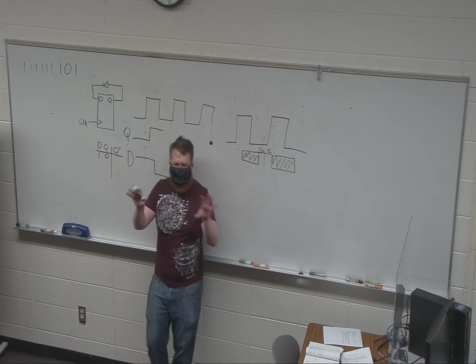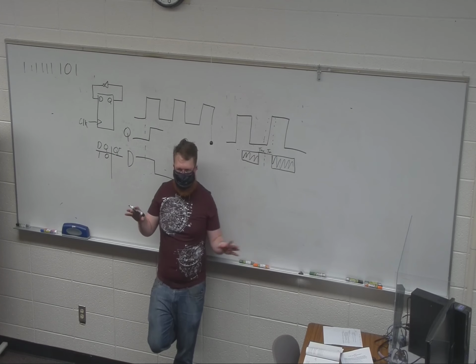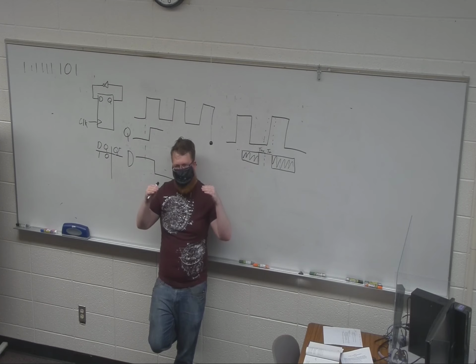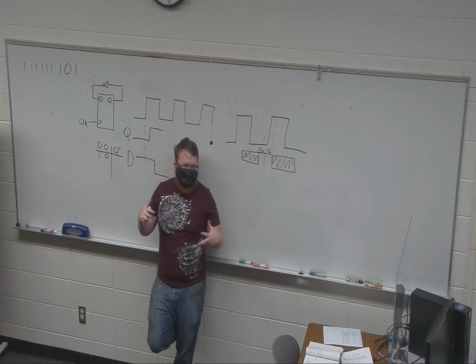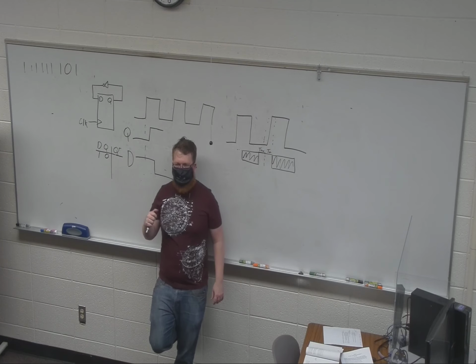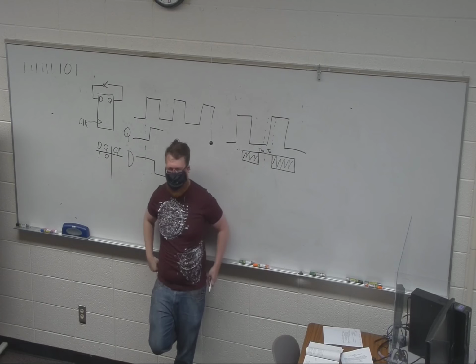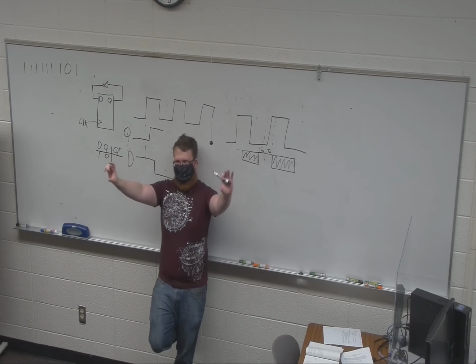But the power supply distribution of an FPGA or any digital system is actually fairly complicated. And even small variations in that power supply can change the speed of these flip-flops. So a lot of difficulty in designing large digital systems is making sure that you can meet timing constraints. And you'll see this error all the time once you get into digital systems: I cannot meet timing constraints.